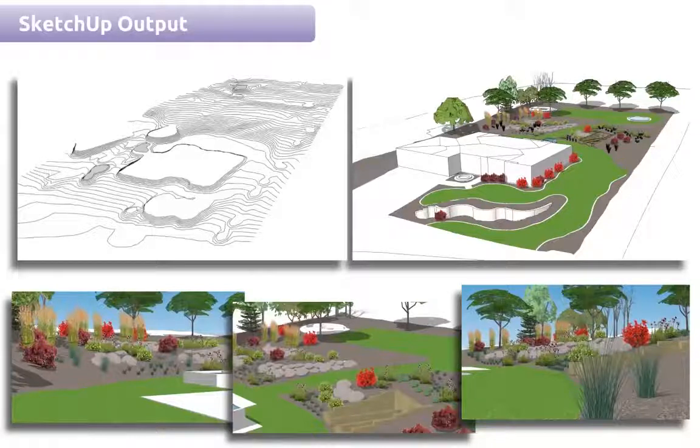And then the GeoTIFF, that's merging all of the images, actually is the most time-consuming process. A lot of times we can do that outside in Photoshop, which might do it a bit faster. But for getting the model and the point cloud, that's a good frame of reference, with a powerful computer, but not ridiculously powerful. If you're running Lumion or 3ds Max, then your computer is almost certainly powerful enough to process this.